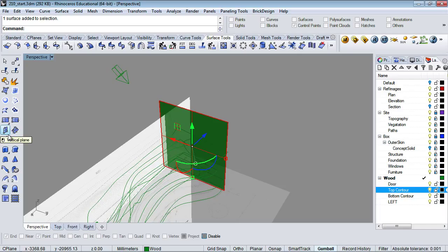So sometimes when you start messing with construction planes, you have to kind of remember, and always look down here to this bottom corner so that you can get an idea of how that's actually laying out. In this case, the x and y, because it's orthogonal, is not different from the world. I just want to basically say, work on this plane, okay?